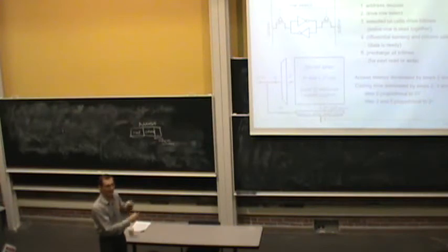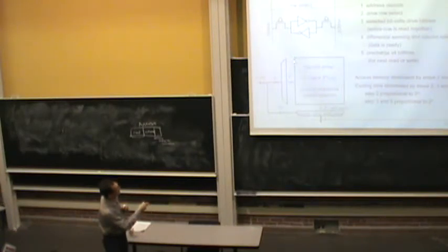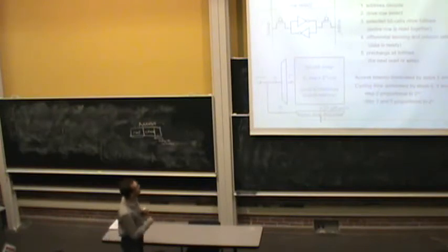If you have a fixed size memory, you don't want to have only one column because now your address row decoder takes too long. You usually equalize this array size, the size of the rows total and the size of the columns, to minimize overall latency.